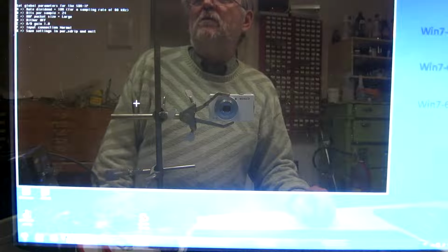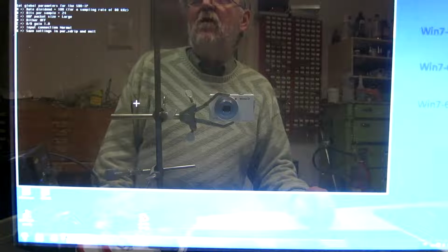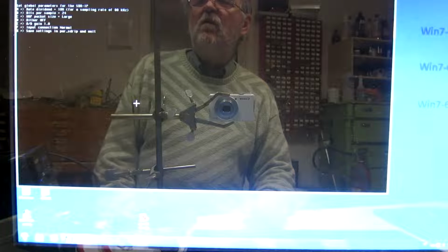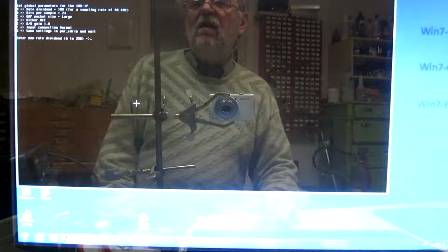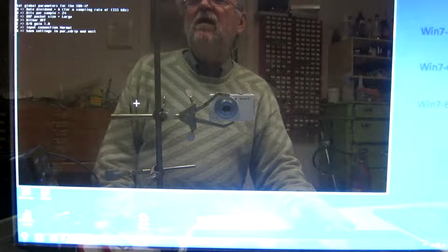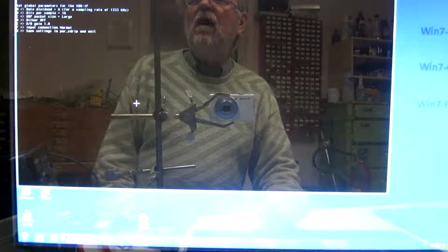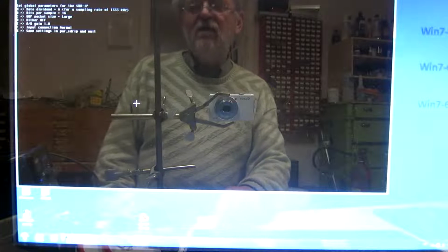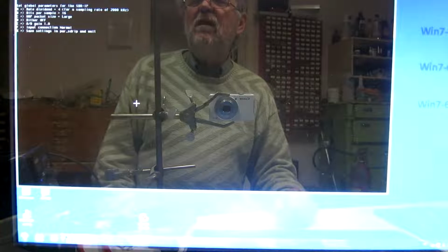Set the global parameters. The rate dividend, the smaller I make it, the faster sampling speed I will get. I want to select a small rate dividend, that's A, and it goes from 6 to 250, so I make it 6. And that gives 1.3 megahertz sampling rate. I could change B to have 16 bits per sample, and if I do that, I get A all the way down to 4. And I prefer to do this.